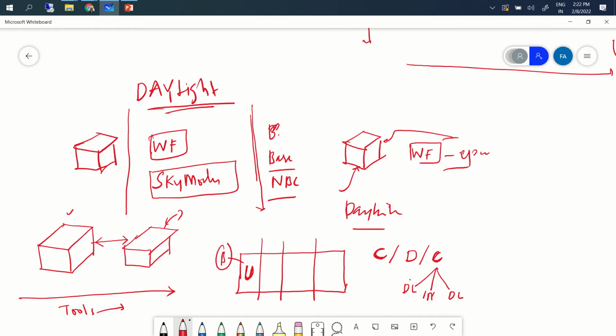So you have a fair understanding about all this, and then once you generate results in terms of lux, apart from knowing that we should have 300 lux or 150 lux or 600 lux based on codes like NBC, you also know how to read the results.